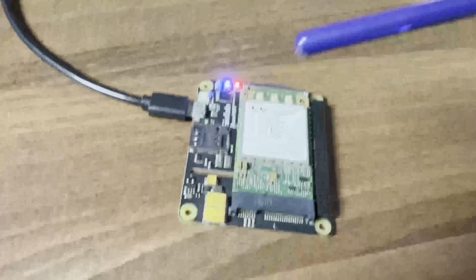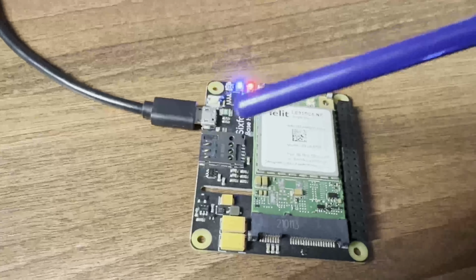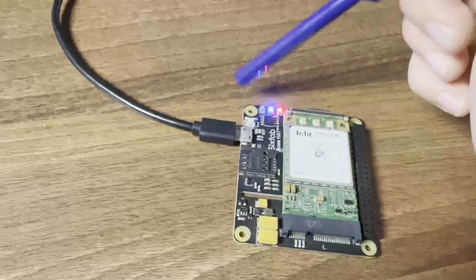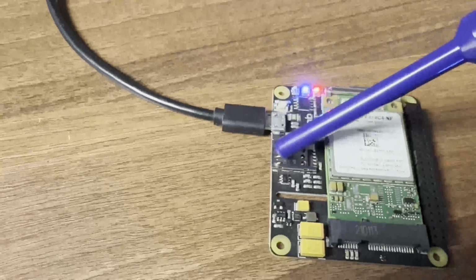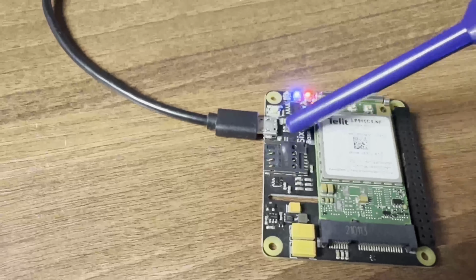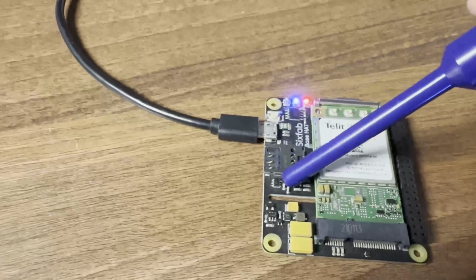So this is the broadband electric field probe, and this type of probe is polarization insensitive, which means it doesn't matter in what orientation you're looking at it. It's gonna give you pretty much the same response.